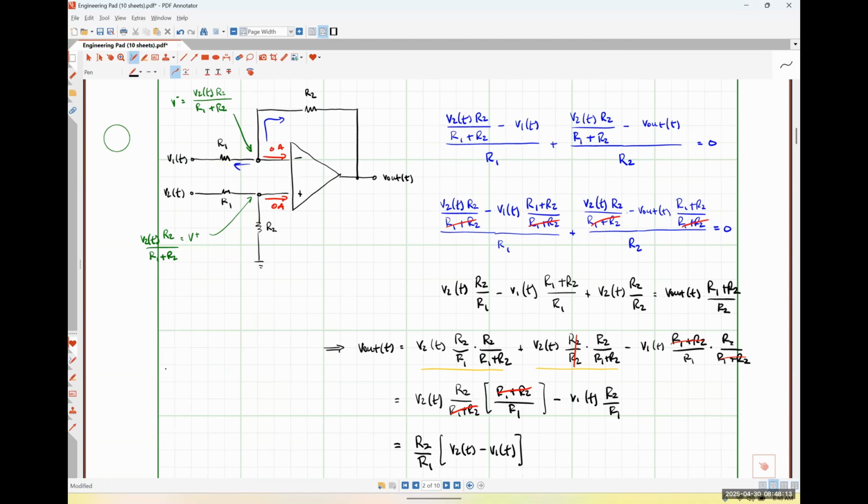If V2 is on while V1 is off, we have a voltage divider being chained into a non-inverting amplifier. And then we would just sum those two outputs together and we would get that exact same result.